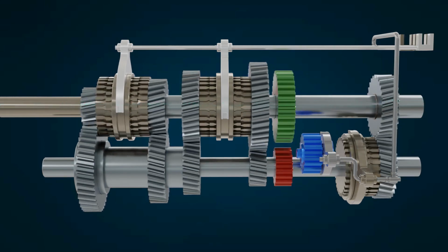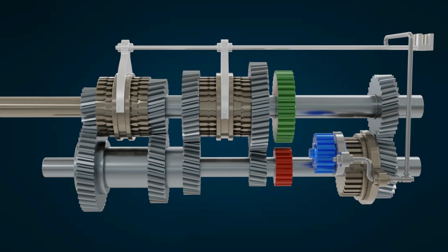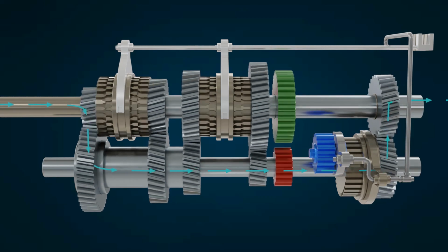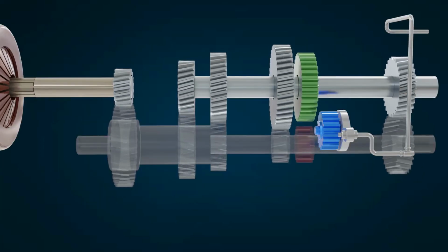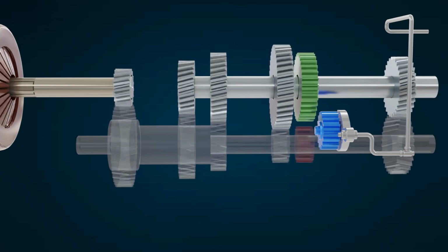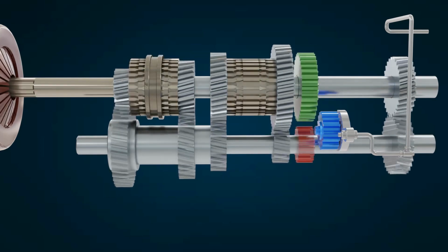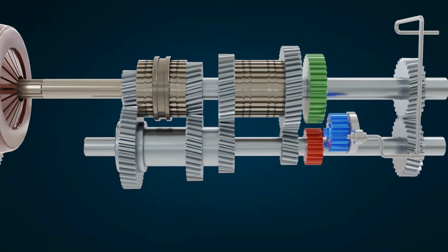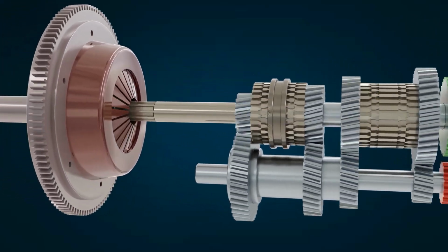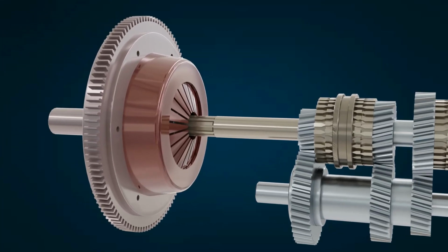Gear ratios of less than 1/1 are overdrives, or increases in speed and loss in torque. It's interesting to note that in the fourth gear, the input and the output shafts are directly connected. The art of holding the gear loosely on the shaft effectively and smoothly lies at the heart of the manual transmission.